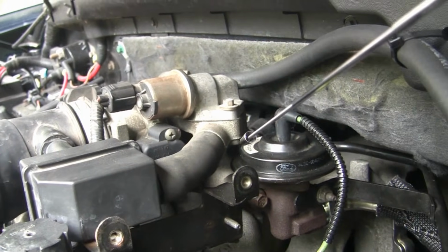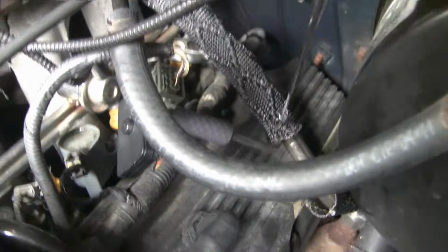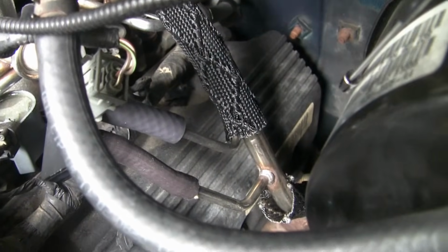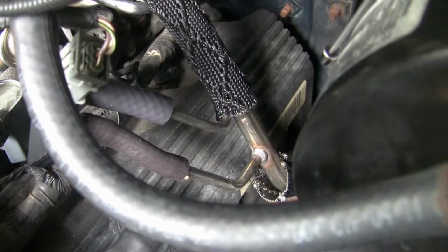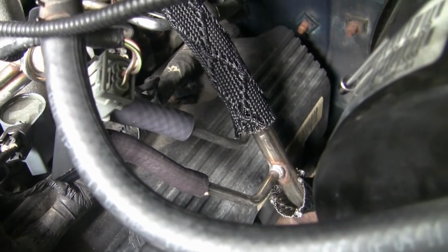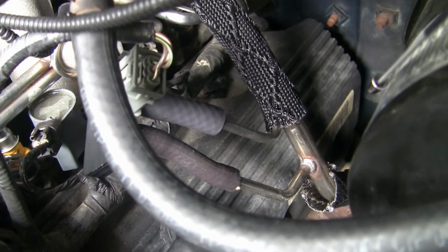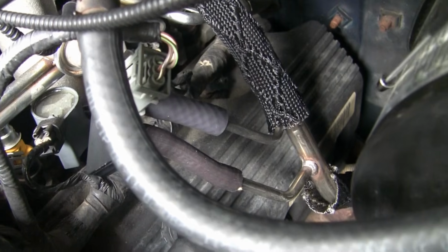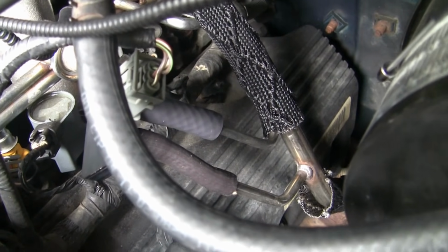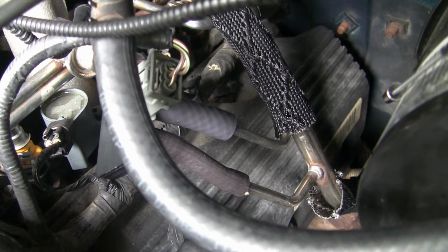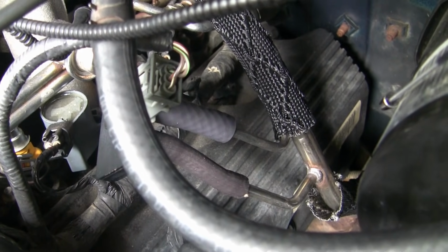The other thing, if your throttle body is clean, I guess in theory it's possible that your EGR tube is actually clogged, and that's the part you're going to have to get from the dealer. I've never seen a video where they've had a case where the EGR tube was clogged. However, the so-called mechanic I took this thing to, he just started throwing parts at it, and that's the first thing he replaced on there. Charged me $60 for the part and $120 in labor, and I got a mile down the road, and guess what? The P0401 code came right back on.